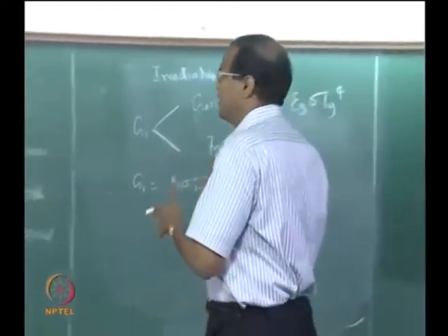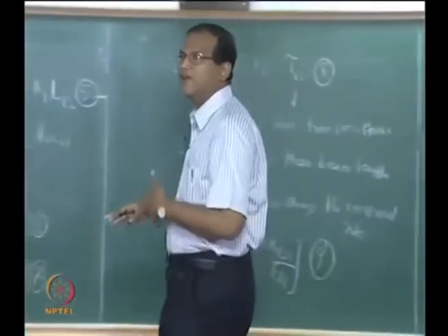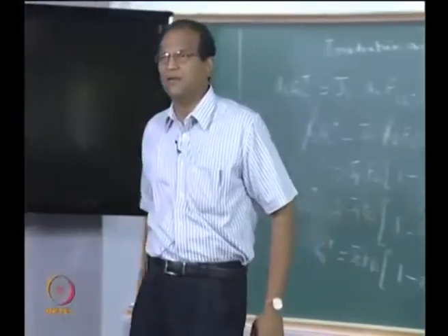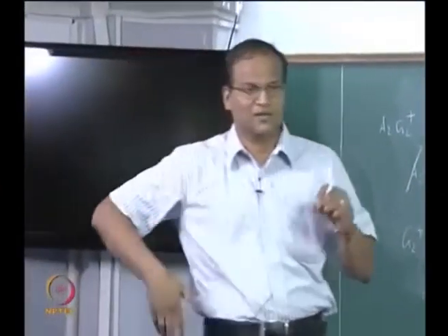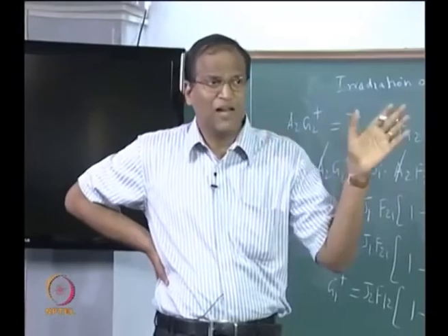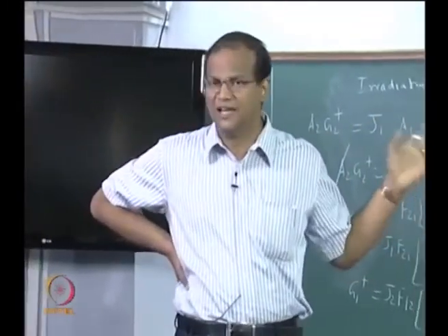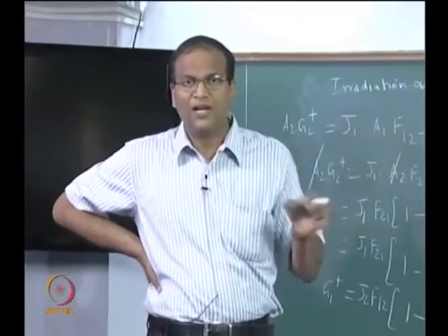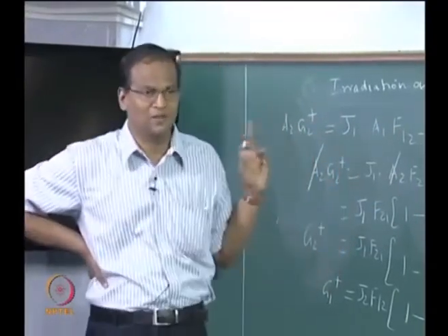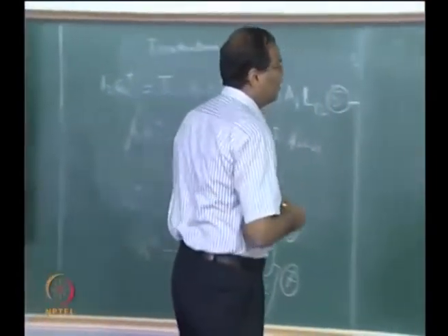So this is to help, it is a simplified way, just like you have a lumped capacitance system. You say the whole body is at one temperature. It is also valid under some limiting conditions, the Biot number hL by k is less than 0.1. Like that, this is valid for an optically thin gas, only one gas, it is not for a gas mixture. Okay. Now J